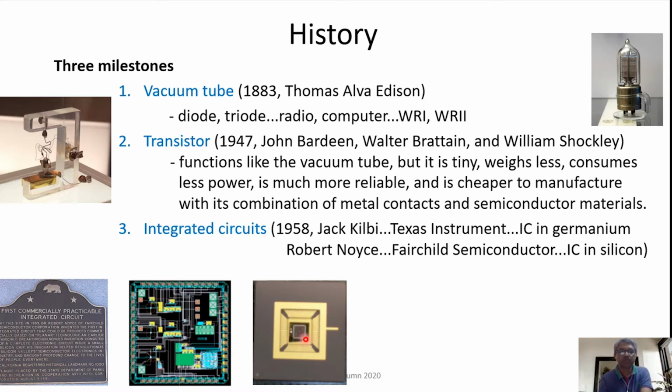So we can put the chip in a package. This is a package, and the chips contain pads. You see these are pads, which are basically the access points of the circuits present inside the chip, and we can then bond these pads with the connections present in the package, and use this to access the circuits present inside.